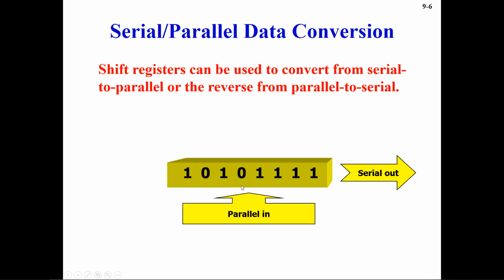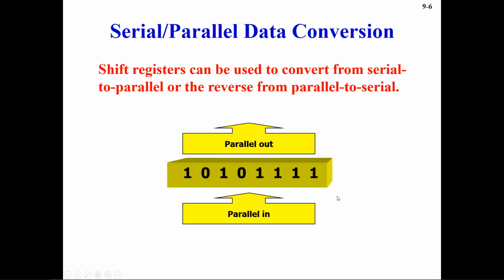And then we have parallel in and serial out. Your input is sent in a parallel form. So in parallel you change all these 8 bits, and then you take the output serially, one by one, from here. And then this is another type in which you input the data in parallel. You directly feed some input into this 8-bit, and then you take out the output, whatever the change, the new 8-bit data, directly from this type of shift register.